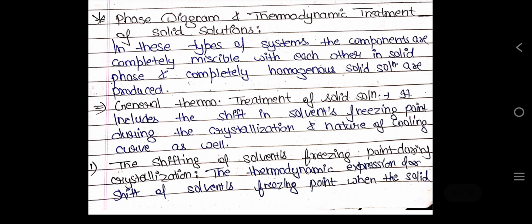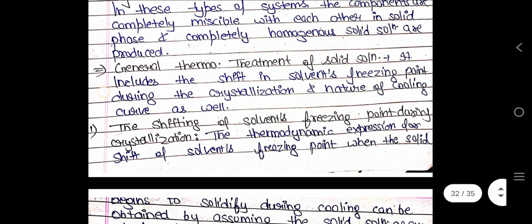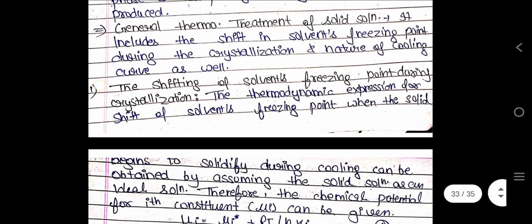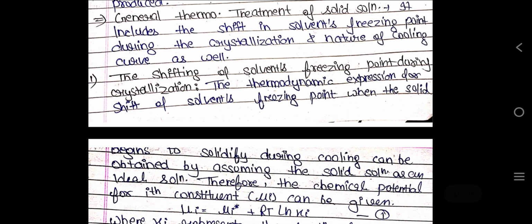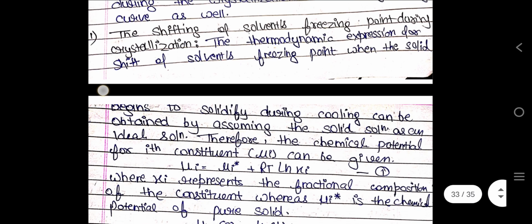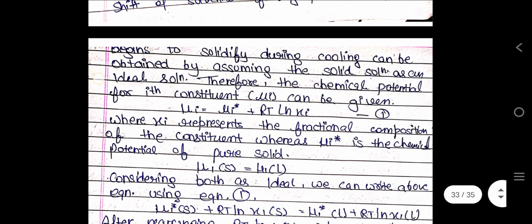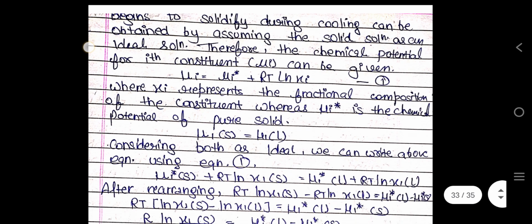If the liquid mixture with composition Y is allowed to cool down, it will do so keeping its composition the same until point 2, where compound B just starts to separate out as solid. Solid B plus solution convert into solid AB2. Therefore, formation of compound AB2 will start, and since three phases coexist at this point, point Q also becomes invariant. Point Q is called the peritectic point.